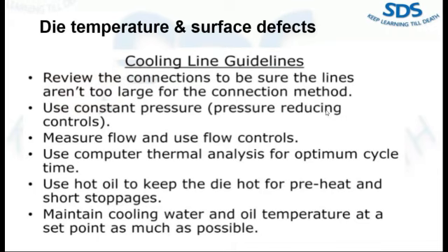This is a small example which I have seen, and logically, in some fluid calculation or heat transfer calculation, you will also find the flow of water is more important as compared to water temperature to transfer heat. All right. So always keep in mind, don't try to keep the water temperature down. Just keep achieving your water flow. Okay.